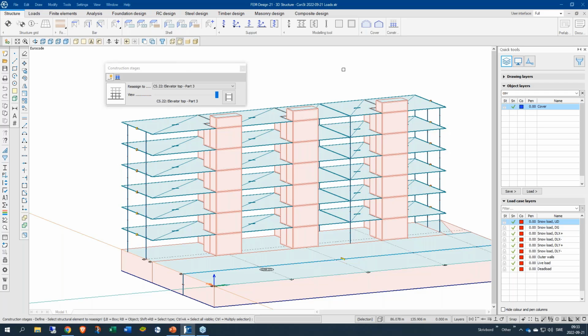And as we could see with the live loads, that I got a little bit of a positive moment, but if I would have just applied the loads on the structure when it's fully built, which is not really the way it's done in the real world, as the dead load of the elements will be added on for each story built or for each part of the structure built.